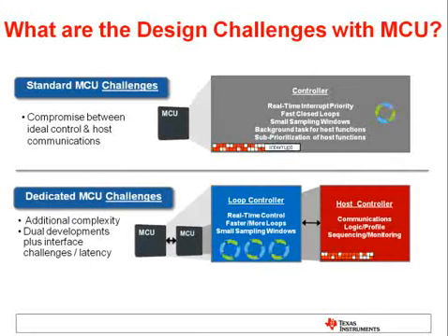A second solution is to use two microcontrollers, a host microcontroller taking care of communications, monitoring, and other system functions, while a second loop microcontroller focuses on the real-time control aspect. This solution provides clean partitioning but adds cost, complexity, and latency from communication between the two microcontrollers.